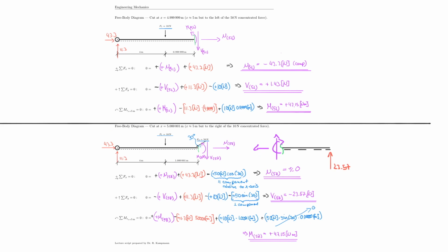Why did I show you this? Because in an exam, after I really studied these problems in depth, I would definitely use this cut and not this cut if I were to solve the problem. But here, this was an educational example, so we tried to show you extensively why and how we calculate these numbers. Later on, when you're more proficient at it and after you have some practice, hopefully you can find shortcuts. For example, cut the right side instead of the left side when you are asked to find internal forces at a specific location. But for now, I believe this concludes our first introduction to internal forces.